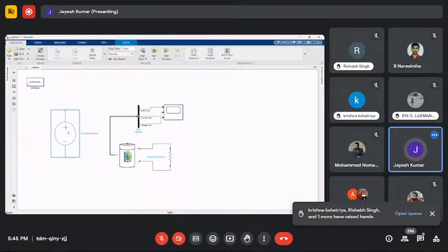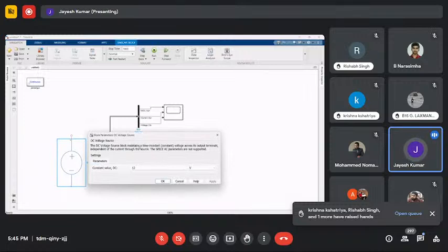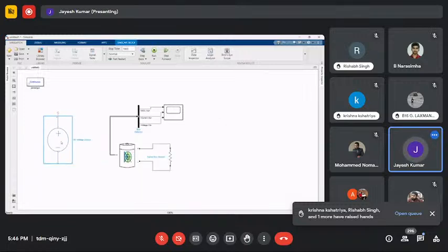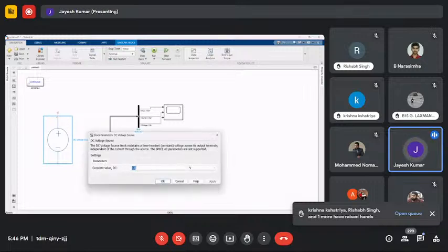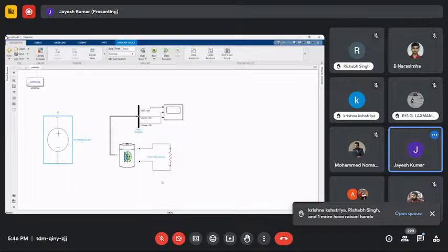And now I start connecting the power supply to the battery. First, I have to convert the battery supply, and then I have to provide the supply of only 7 volt, because this battery should be at 7.2 nominal voltage. So the voltage limit should be that much only. So I change this 12 volt to 8 volt. And now I connect the power supply.